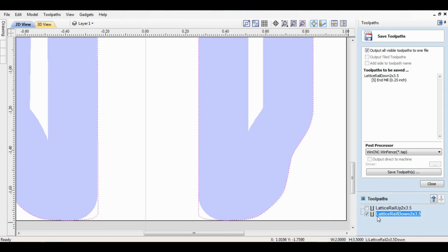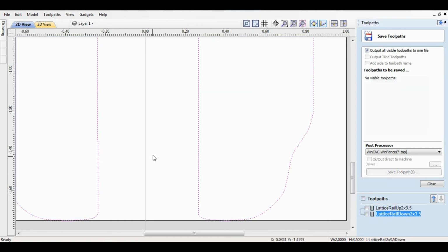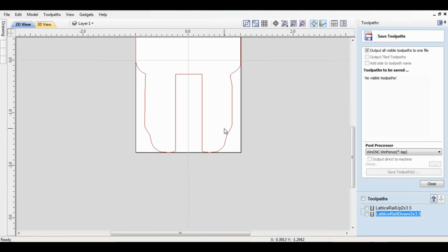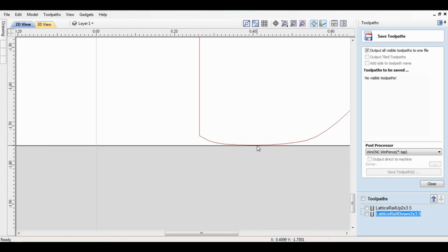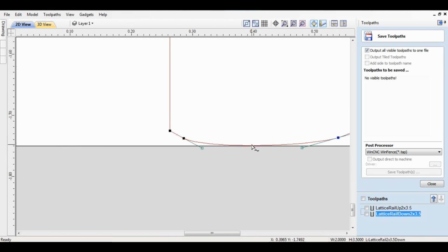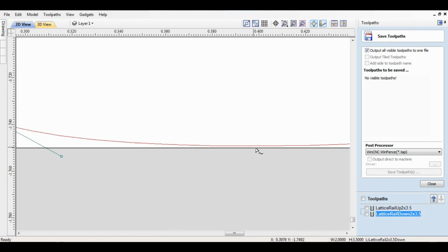Probably the best thing to do in that case would have been to cut that center tongue section out. And the way that I would do that is probably to come to here at the lowest section of this. I'm going to select this, and I'm going to hit the letter N as a node, and I'm going to cut this right here in this lower section. And I'm going to try to find the lowest part, and I think that's right here.